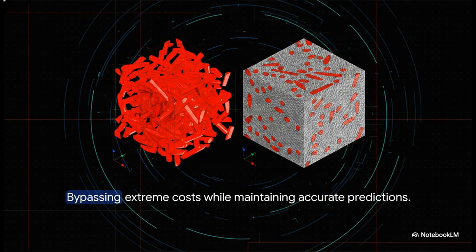The results show that the proposed method accurately predicts elastic properties while completely bypassing extreme computational costs and practical difficulties. In the time it took to generate and run just one incredibly heavy RVE simulation, assuming the meshing didn't fail, of course, the orientation averaging method delivered highly accurate results in literally seconds. To put that into perspective, simulating 10,000 unit cells using this method took around 115 seconds on a standard laptop. The self-consistent interaction model in particular frequently nailed the actual RVE results right between those Voigt and Reuss extremes.